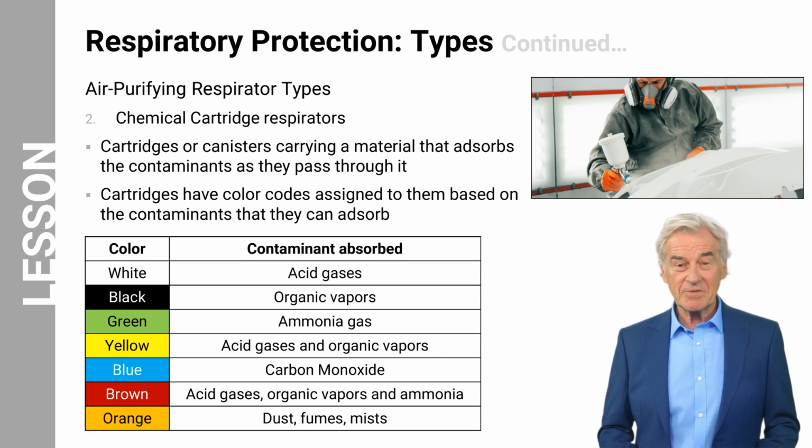It is important to remember that chemical cartridge respirators have limitations on their use. You should not use a chemical cartridge respirator in an oxygen-deficient work environment or in an environment where the specific type of chemical cartridge cannot absorb the contaminants.